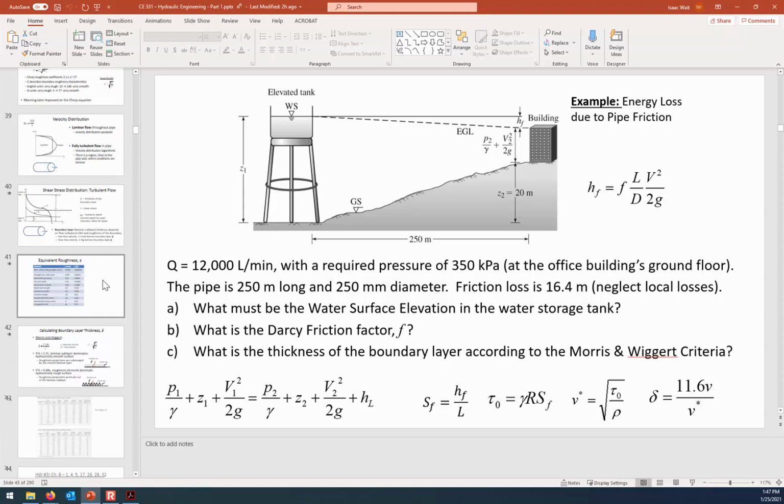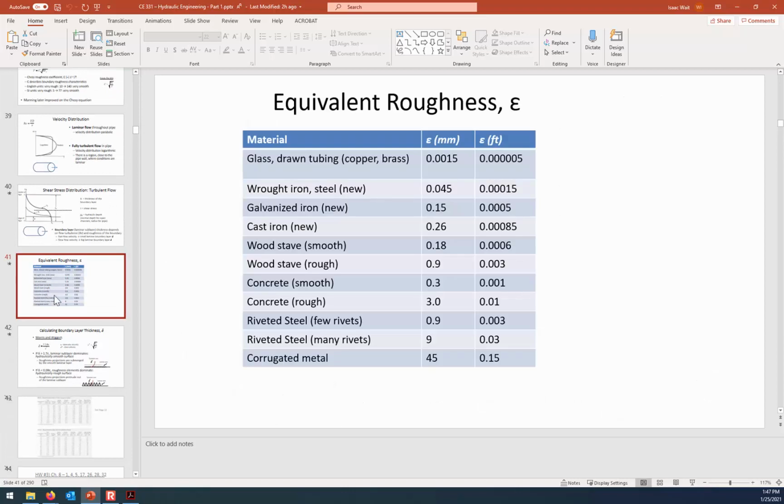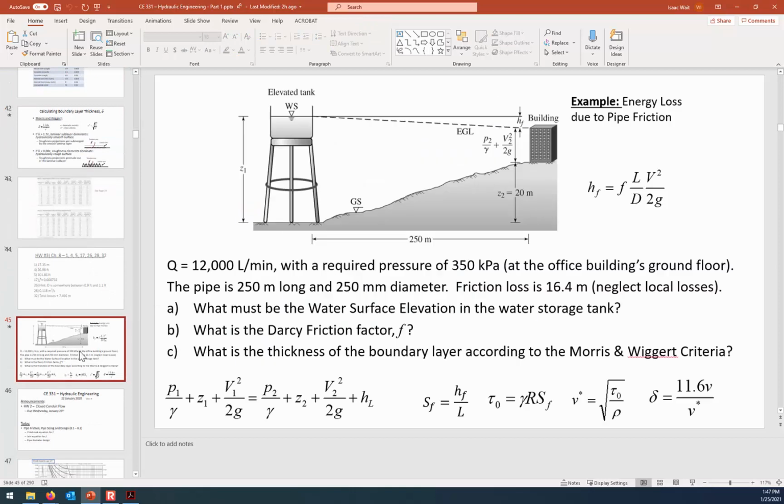Okay, we go back to this table. This pipe has a roughness, according to the calculations we just did, of 0.25 millimeters. So most likely, this is a cast iron pipe. The example didn't actually tell us what the pipe was made out of, but now that we know it's cast iron, and we've got the F value, we could calculate the hydraulic situation for a variety of different flow rates.